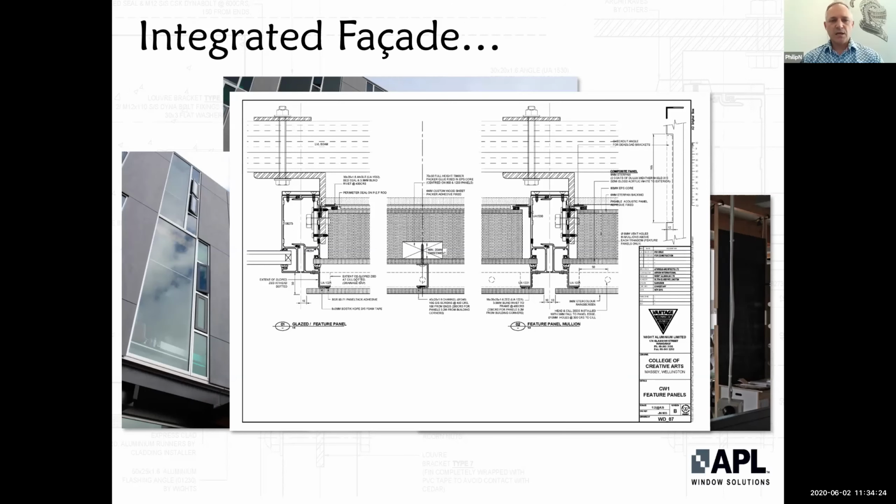So you can see the bottom is the outside and the top is the inside. On the bottom, you can see that double skin scenario with the cladding, and one of them is projected out onto a rain screen using a series of clips. And on the inside, they've got that insulating panel, and they've finished it off with a pin board on the inside so they can use it inside the classroom environment.